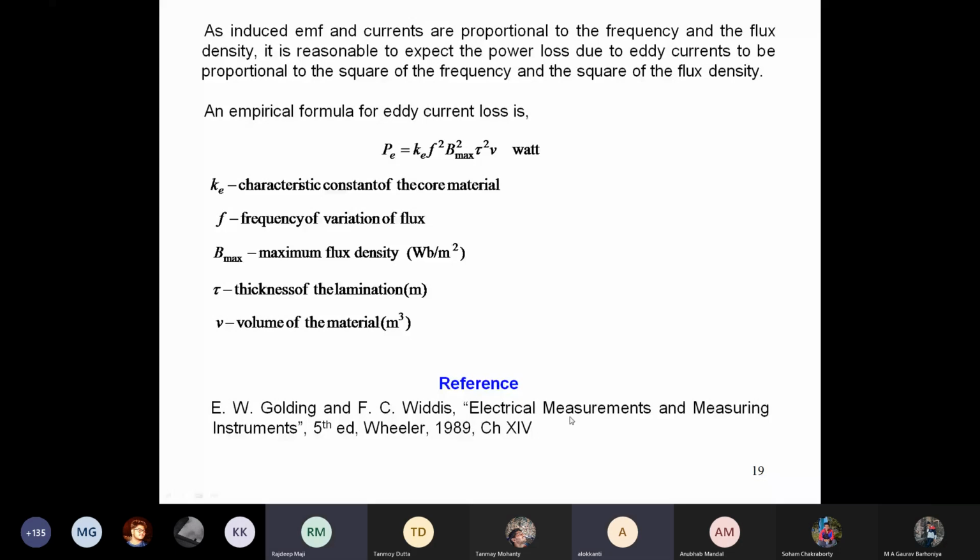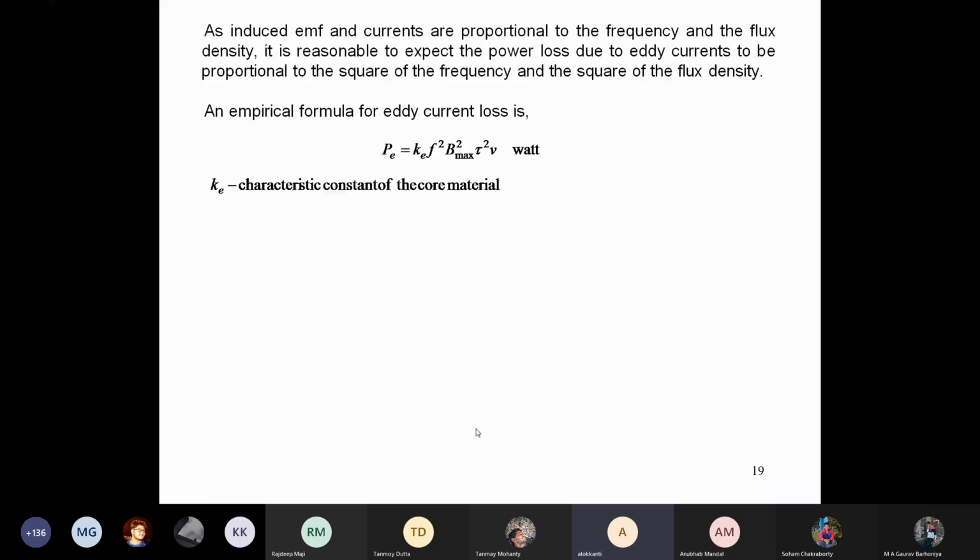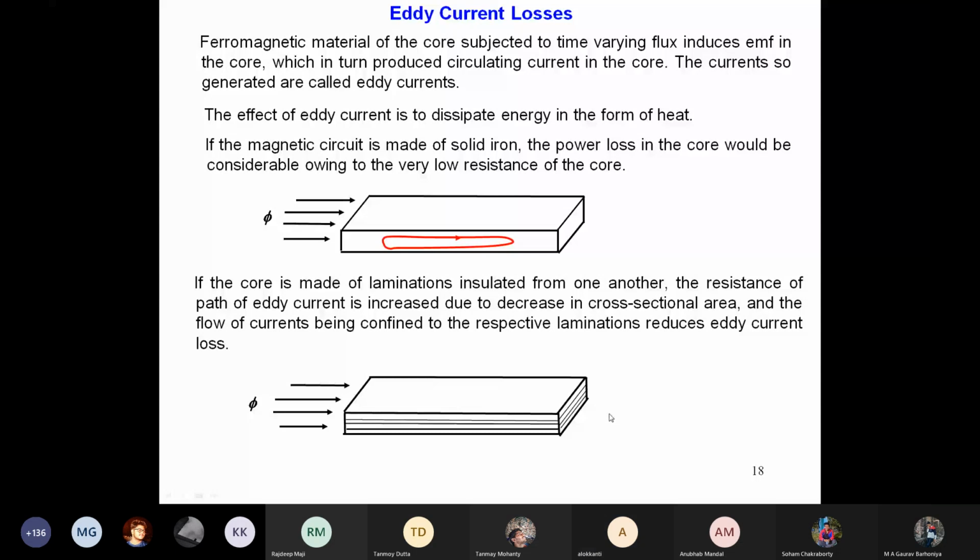Okay. So is the eddy current loss in each plate equal? Eddy current loss in each plate, assuming that they are equal, because we are not varying the thickness. Okay, so this is the eddy current loss for a uniform solid laminated core. If you remember the picture in my earlier slide, instead of such a solid core, we will have such a laminated core, and assuming they are uniform, of the same thickness, then that is the formula.